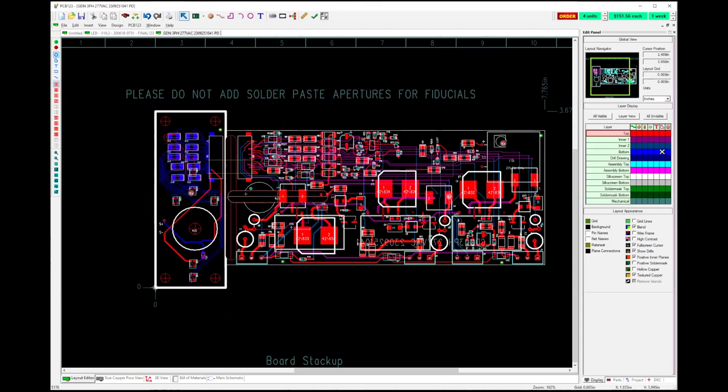And this will give you the ability to make a, you can make this a zigzag for creepage, high voltage protection, that sort of thing. You just put 2 or 3 in here. You can rotate it to whatever angle, give it a different angle if you want.